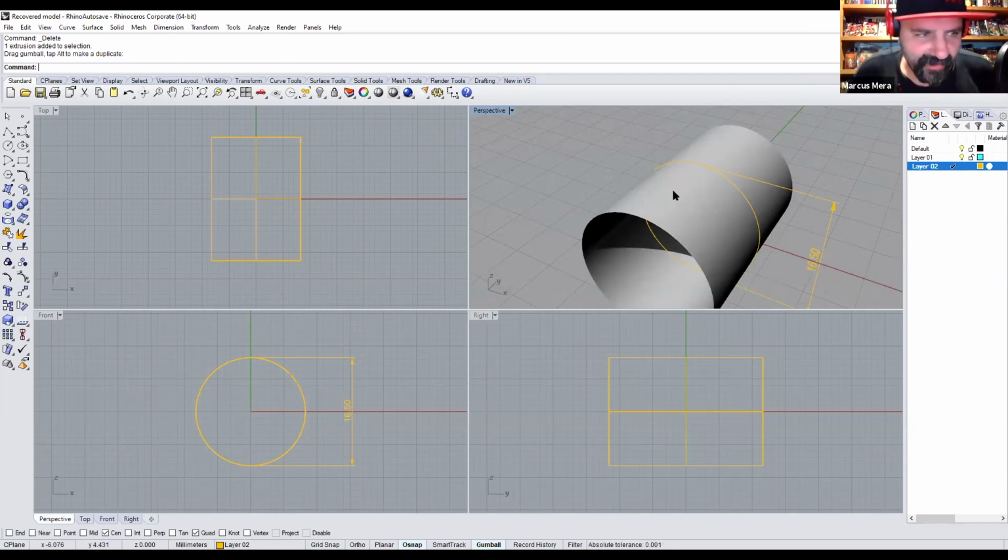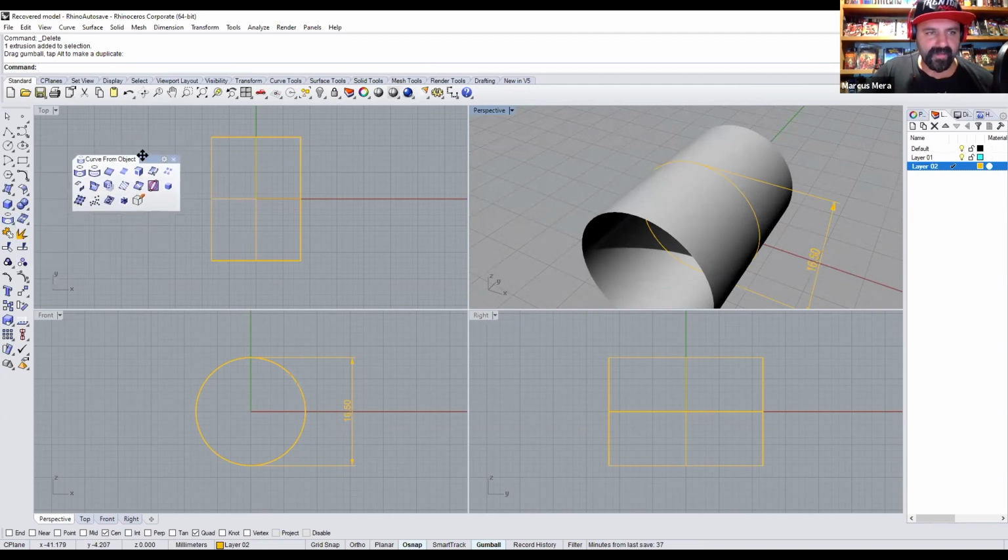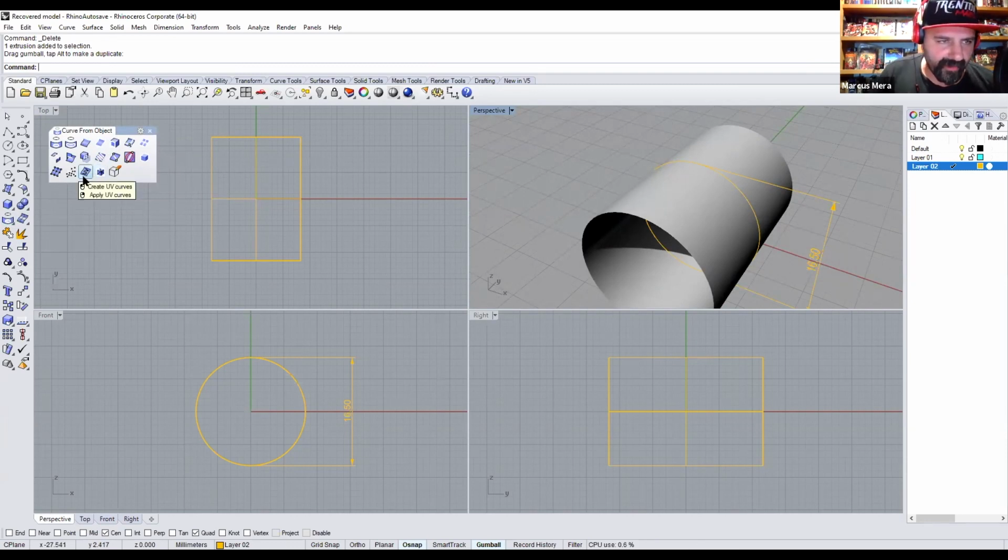All right, guys, here's the command. Pay attention now. We're going to go under project to the curves. As you can see, it has a little arrow on the bottom. That means there are more commands. So when you left click on it, it pulls up a drop menu. And if I left click on the top of it, I can move this palette around and dock it here, whatever. This command right here, I'm highlighting it. It's the UV command, okay? And if I left click on it, I'm going to create UVs.